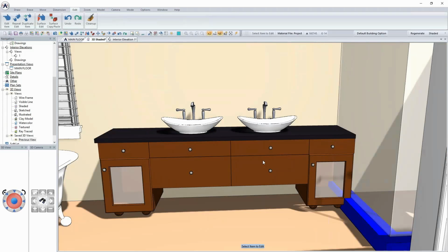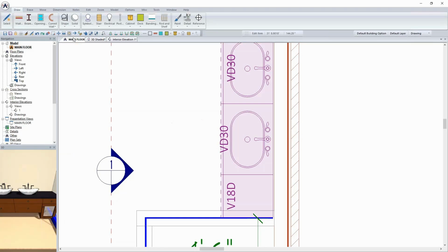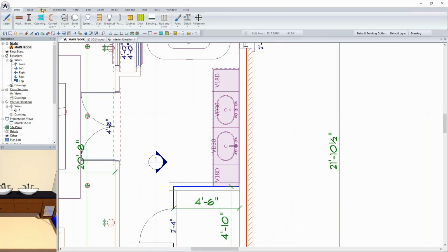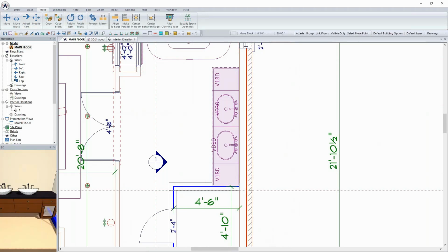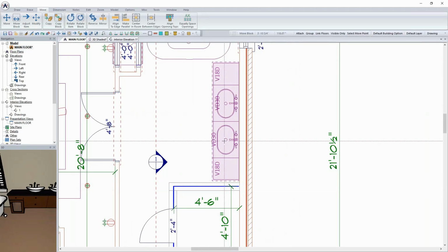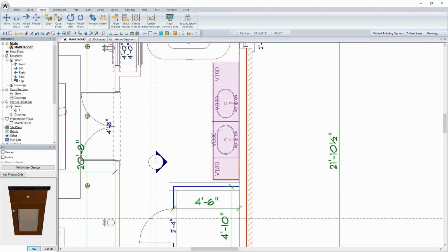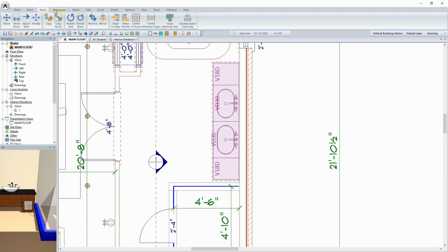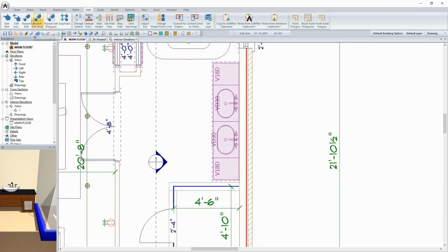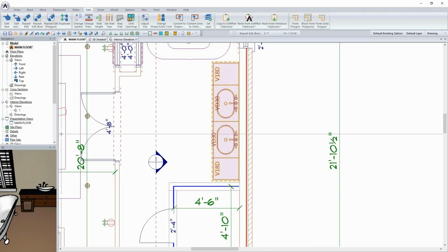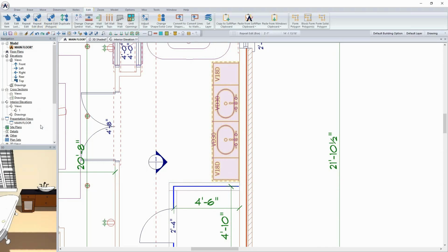We've managed to lay out a shower. We've got the bathtub over here. At this stage I'm going to move the vanities away from cleaning up to the wall, and I'm actually going to come in here and remove them from the cleanup option. Because I'm doing that, it will prevent the vanities from actually finding the wall, and that's why they're moving to it, simply because they find the shower wall and they're snapping down to it. I'm attempting to get it so that it's centered inside the room and no longer finds the shower wall over here.